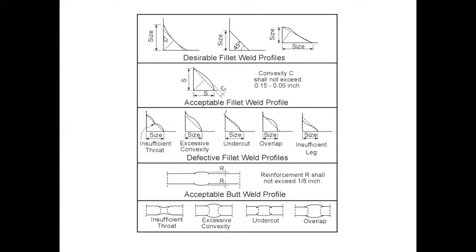effective throat on the inside. So we basically can hide this weld inside of here. We see there's a little extra here and here, but that actually can be quite helpful, this little extra bit. What it does is it helps create nice flowing lines for the stress. You're not seeing a hard corner or a notch effect. So if you have excessive undercut on one side of a weld, that can definitely cause notch effect. That's something we're trying to avoid.